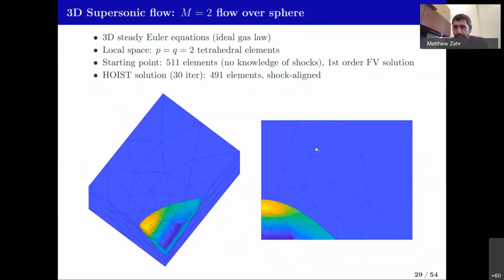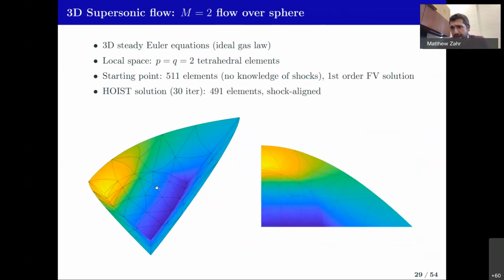And then after about 30 tracking iterations, we get this bow shock tracked pretty well. I'm now going to look at just the shock layer, removing all of the constant flow outside of it. And you can see that we've got a high-order approximation of the boundary, of course, but that's just from mesh generation. But we have the high-order curved approximations of the actual bow shock that comes from the optimization approach.